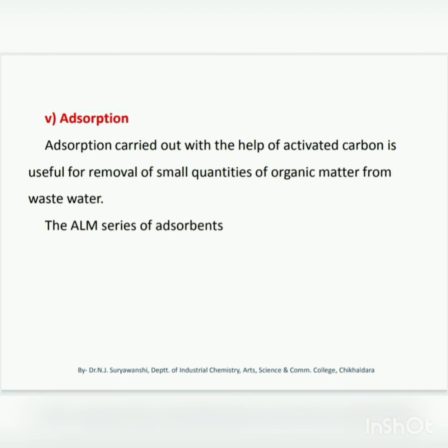Activated carbon treatment is particularly effective for the removal of pesticides like DDT and carbamate insecticides. Adsorption processes using activated carbon, peat moss, brown coal, and other cellulose material also find application in wastewater treatment for the removal of refractory organic toxic metals and colors, etc.